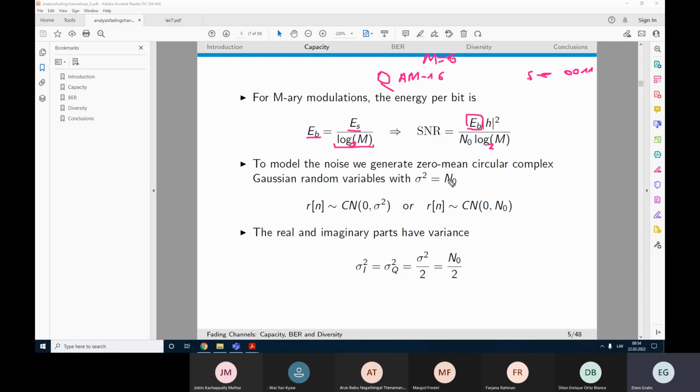So noise is generated so that this power spectral density is actually the variance of the normally distributed process. This is a random process with a 0 mean value and variance sigma squared equal to the desired noise power density. So that's what's happening inside this AWGN function. It generates a Gaussian normal process, randn in Matlab,